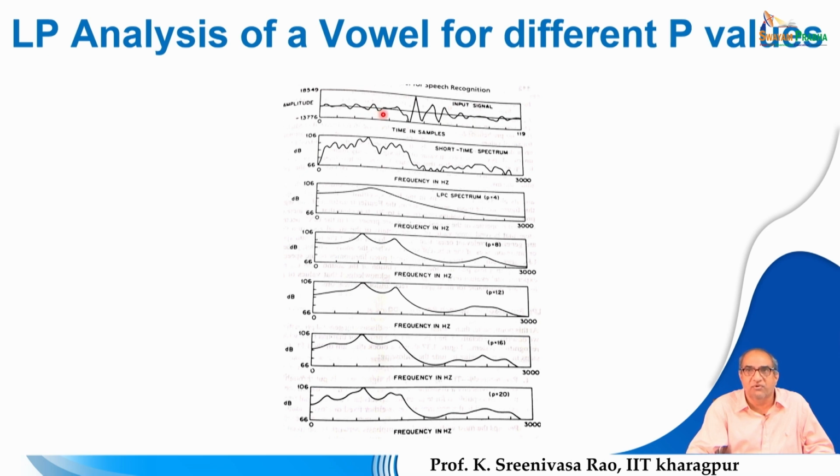We have considered the vowel segment because when you are uttering a vowel, the vocal tract is opened widely, and you can see proper formant frequencies or resonances. You can clearly see the 3 or 4 resonant frequencies, also known as formants, which are the dominant frequencies in the spectrum. So, that you can clearly observe in the case of vowel utterances.